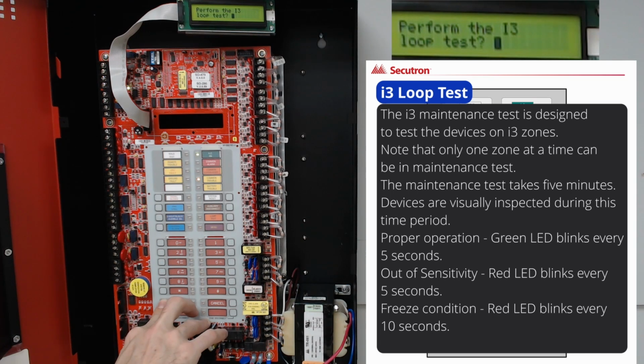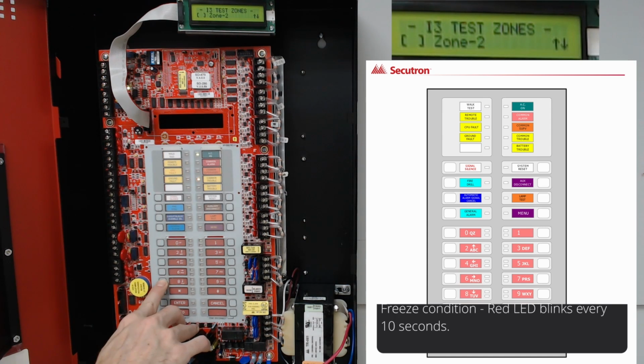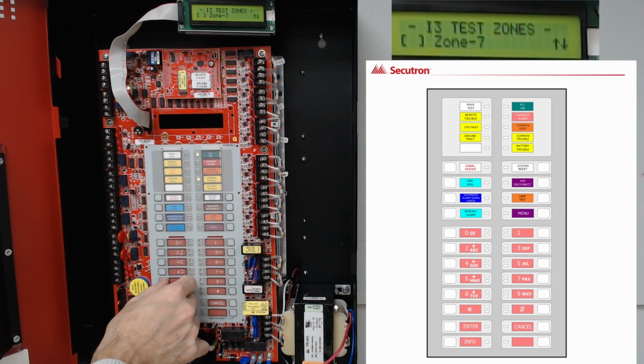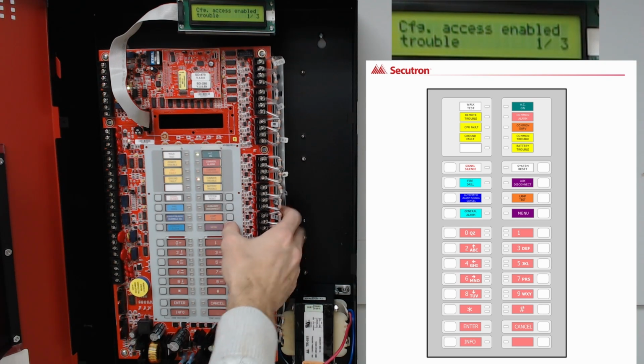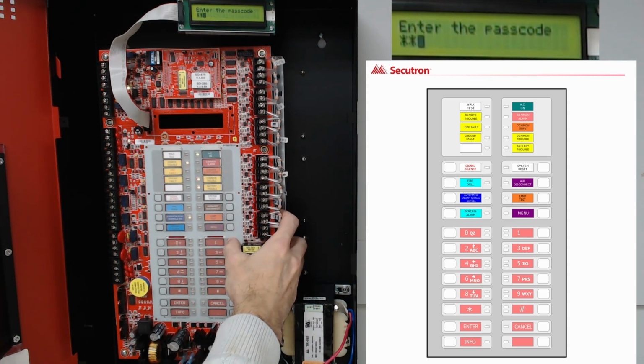Would we like to do the I3 loop test? Select enter. It will then go into the zones, our 12 zones that we have on the panel, and we can scroll through these zones until we find one of the zones that has the I3 device. From here we can press cancel and we'll back out again. Go back into my menu options, hitting my default passcode,